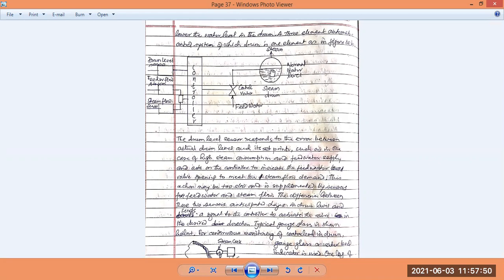So we just sense the amount of feed water and the amount of water present in the drum, and when we have to open the control valve, the water is fed to the upper part of the drum itself. Now, this action is not very fast. It is slow and supplemented by feed water and steam flow sensors.